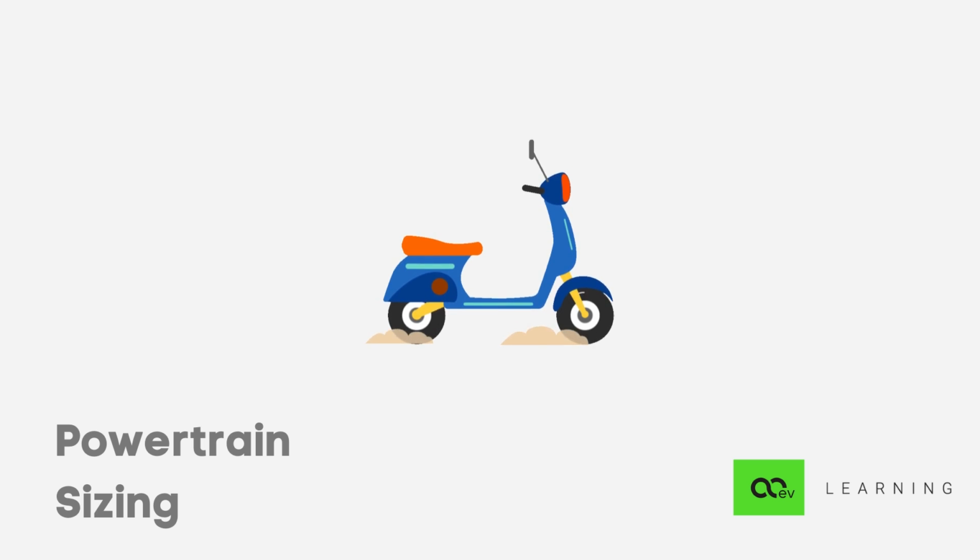Remember, the motors are agnostic to how this voltage and capacity of the battery is arrived at. Thus, it is at the discretion of the battery designer to determine the battery specification and especially the configuration for efficient packaging. The designer can choose the cell he or she wants, the chemistry he or she wants, the combination of series and parallel, as long as it meets the voltage, current, and capacity requirements.